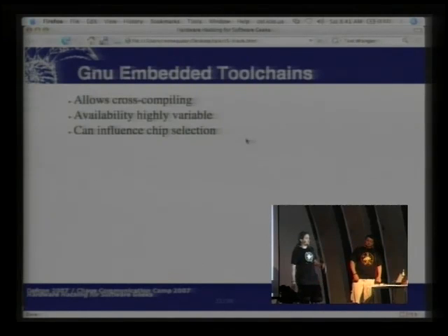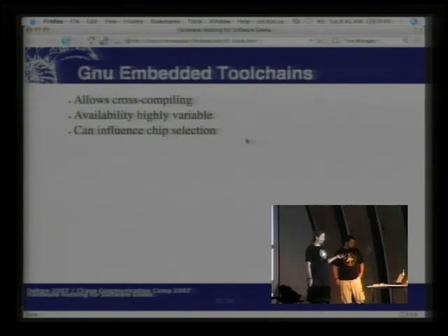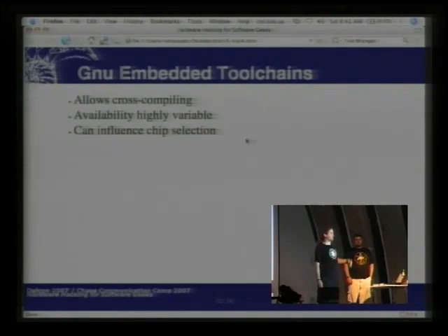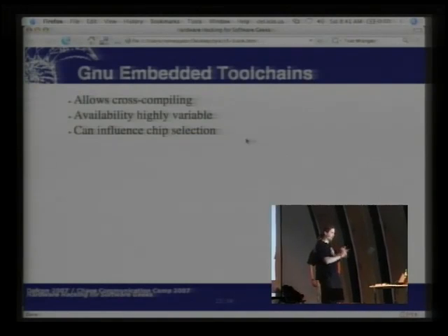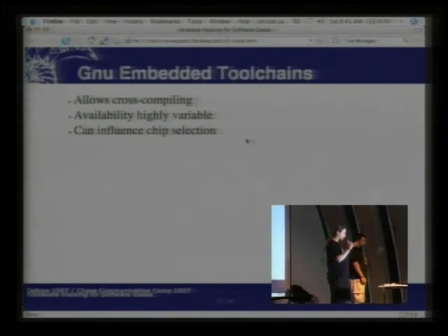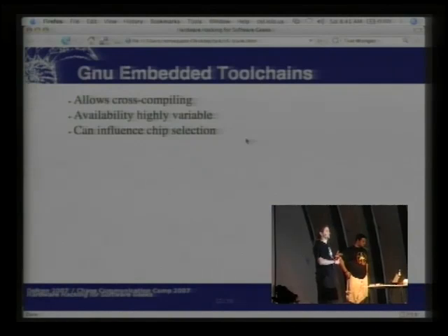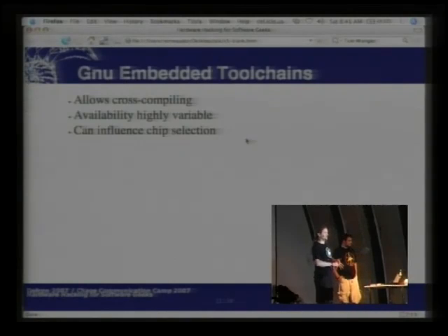The one downside of the development boards is that they tend to have the highest-end member of that chip family on them to give you the full experience, as it were, with all the ports, all the on-chip peripherals, all the things that that family can possibly do. When you move to a production environment, you may end up with a restricted version of that chip for cost reasons. So it's good to keep the eventual target in mind when doing the development.